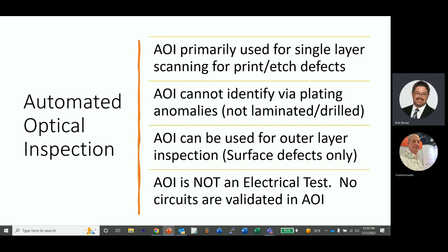It sees all the copper on the board, compares it to the CAD data within some sort of etching factor, and detects any anomalies that may occur. Say there's a mouse bite out of the track, a dimple in the track, any extra copper, or any kind of water stain which makes the copper a little bit different color, that would also show up.